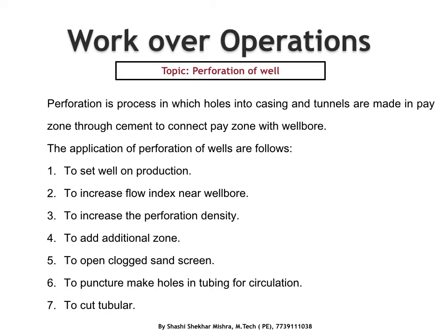Then it is also used in making holes in the tubing for circulation. Suppose the SSD, we are not able to open the SSD and we want to circulate, for acid treatment or any other thing. In that case we make a hole in the tubing to achieve that objective. And it is also used for making cuts in the tubular, like a power cutter.